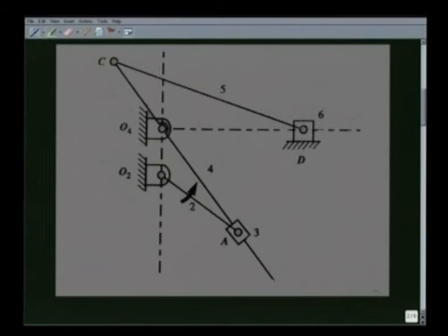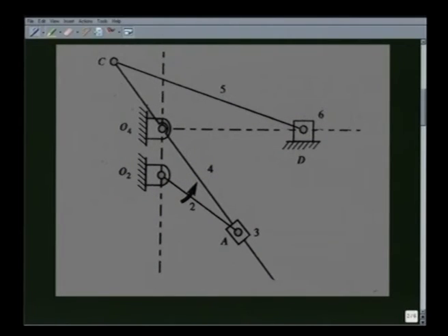This is the kinematic diagram of that Whitworth quick return mechanism. As we see, this is also a 6-link mechanism with 5 revolute pairs and 2 prismatic pairs. This link 6 is the tool holder and link 2 is the input link which rotates at constant angular speed. Link 3 is the block which goes along link 4 at this prismatic pair.